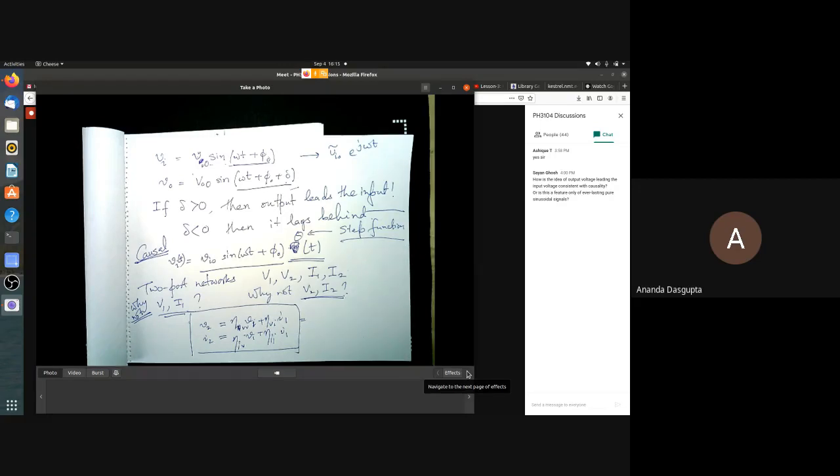Well, there is one situation where this is used, as was pointed out in the discussion forum by one of you. These are called ABCD parameters. In fact, typically we will use V2, I2 as independent, and then you write V1 as A V2 plus B I2, and I1 as C V2 plus D I2. That's where the name ABCD parameters come from. For want of a better name, you can imagine that the only reason why this has such an unimaginative name is because it's not really used very much.